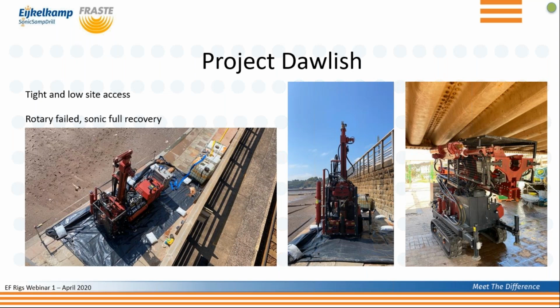And basically, what we're doing is pouring it out because of the big granite boulders all the way down with the concrete layers on them. So we're coring straight through the granite and then onto the concrete pad, about 3 metres, 1.5 metres for that, and then straight through, which was taking us half a day, if that, and then straight into the natural ground, which at the start is a bit of beach sand, and then you come into weathered mudstone with gravel, but it's very, very dense. So you can see why the quarry was getting no recovery. Yeah.